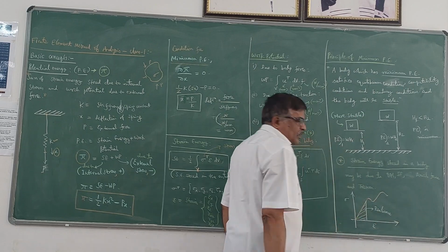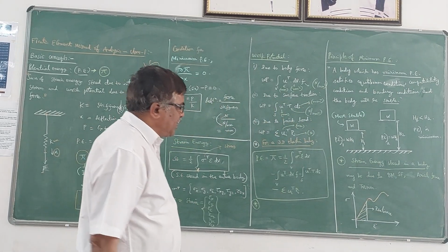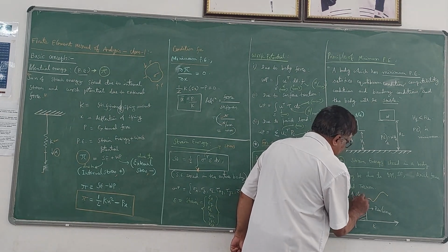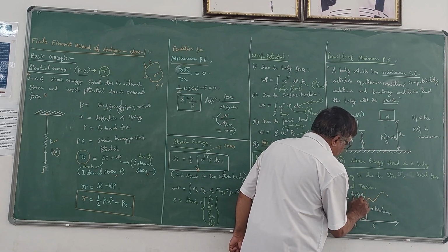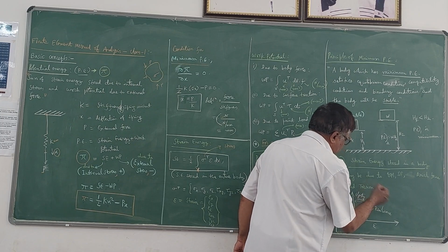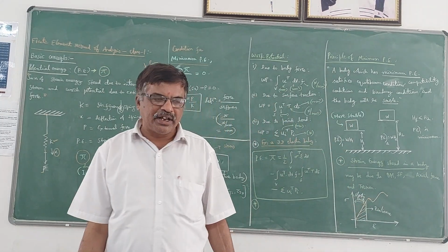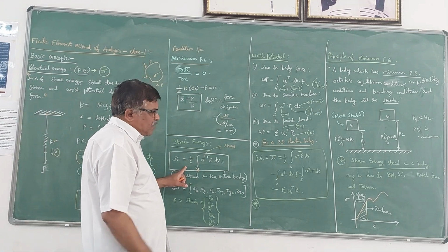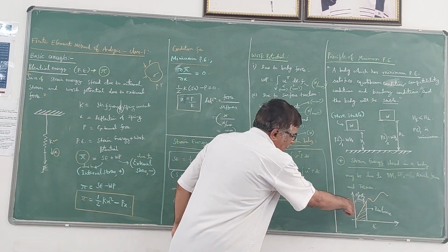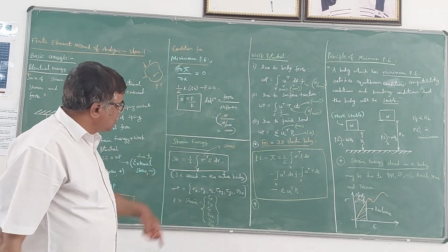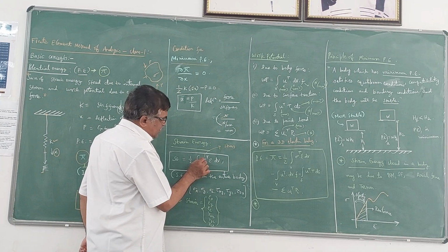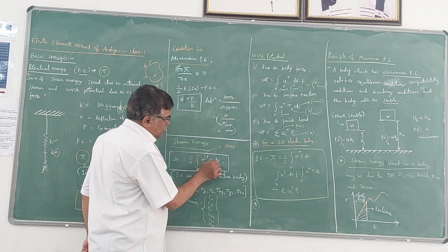That is of that particular material, which means it should be within the elastic limit. So from here to here, it is in the elastic limit. Once it crosses the elastic limit, it goes to the plastic state and permanent deformation takes place. Now this expression we can arrive at by having this diagram. It is half into integral over V of sigma transpose into epsilon into dV.